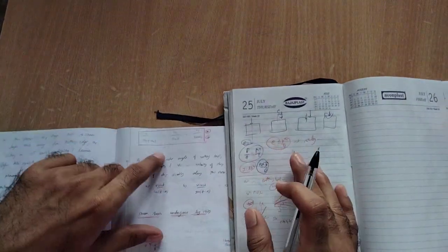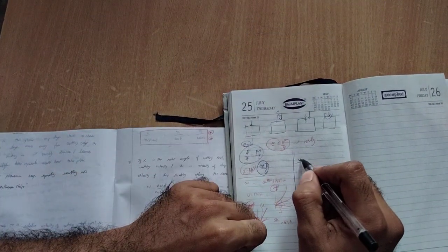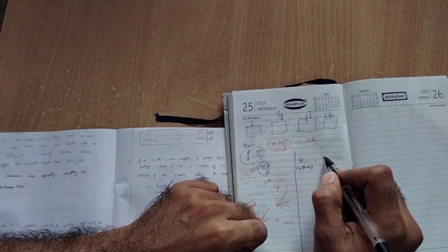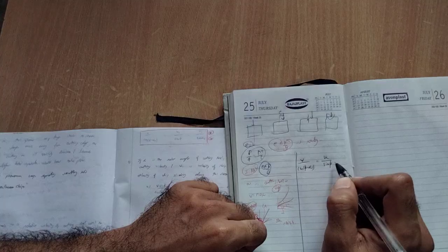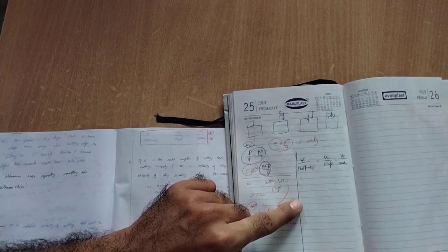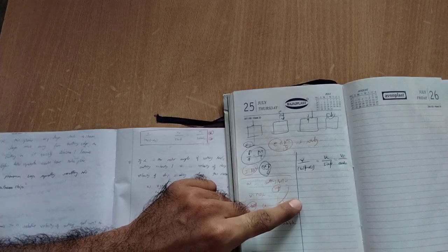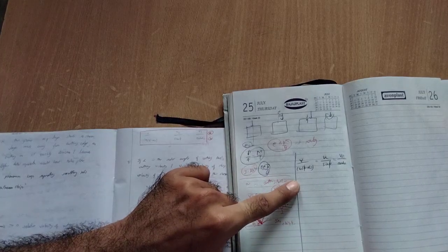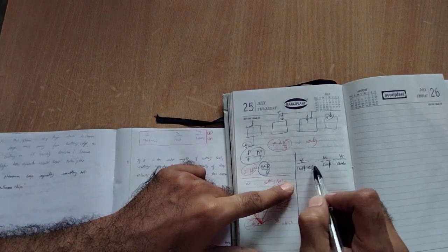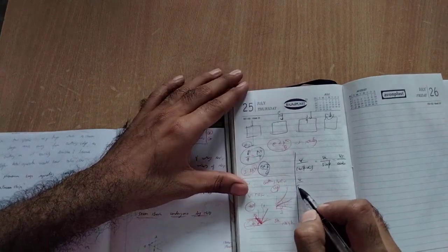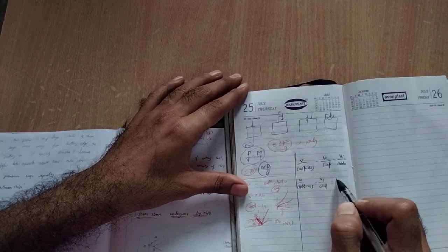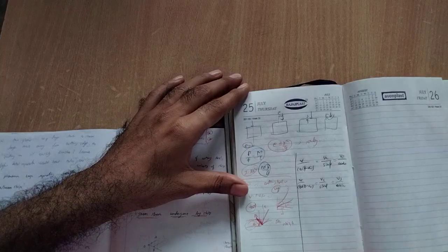Putting each and every thing together, we get the required answer: V divided by cos of (shear angle minus orthogonal rake angle) equals Vc, the cutting velocity, divided by sin of shear angle, equals Vs divided by cos of orthogonal rake angle. This is the main relation that I want you to remember, as most questions are asked on it. V divided by cos(phi minus alpha naught) equals Vc divided by sin phi equals Vs divided by cos alpha naught.